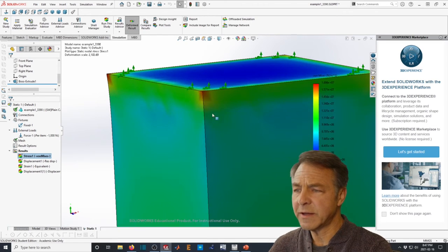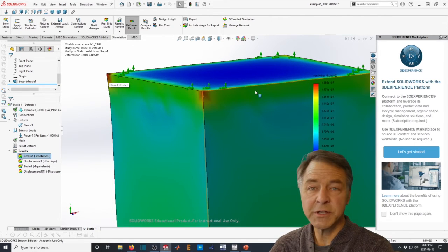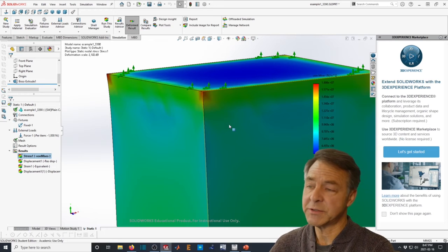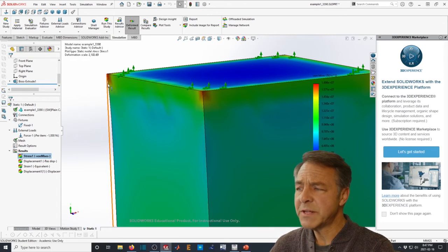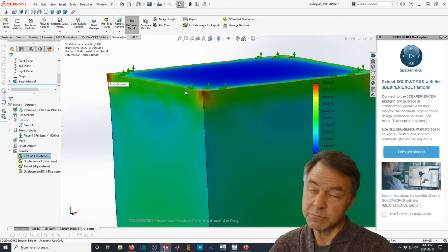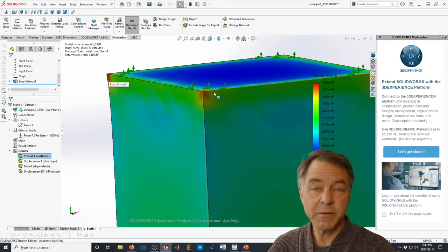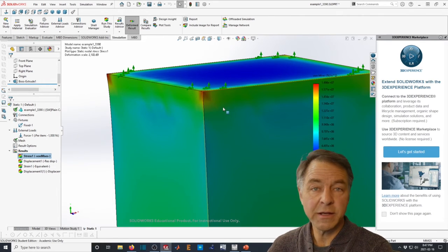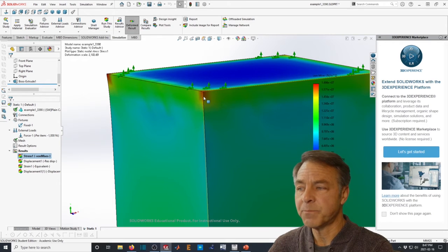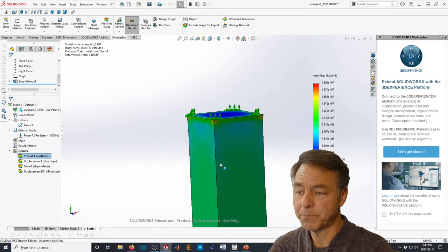You can see that once again, the features that are here in the detailed corners are smaller still because the mesh size is smaller. So what that should say to you is that perhaps these aren't real features necessarily. There is some effect of this, but what we've done is we've created artifacts in the simulation that aren't exactly represented in real life in the way that we've shown them.